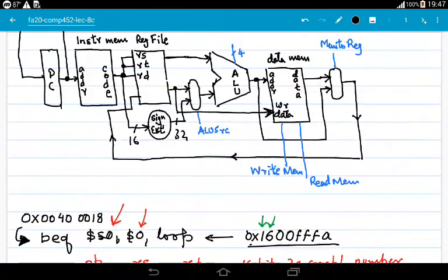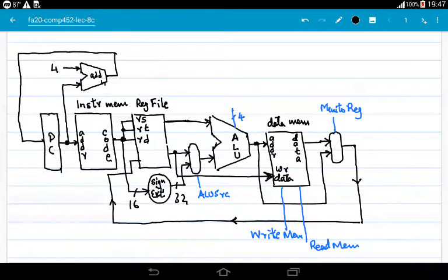and register file outputs the values in those registers at its output port. So here you get 1 followed by 4 zeros. Here you get all 5 zeros. So here you get the value of our S register. In our case it's going to be S0, and here you get the value of RT register, which in our case is going to be the value in 0 register, which is 0.